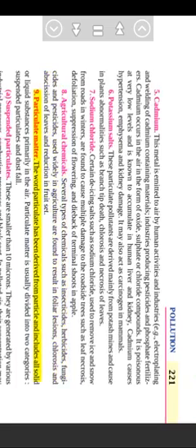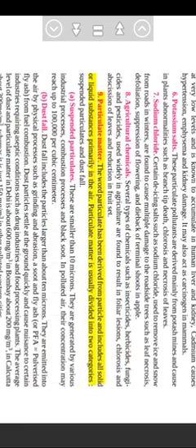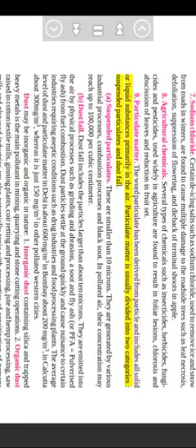9. Particulate matter. The word particulate has been derived from particle and includes all solid or liquid substances primarily in the air. Particulate matter is usually divided into 2 categories, suspended particulates and dust fall. A. Suspended particulates. These are smaller than 10 microns. They are generated by various industrial processes, combustion processes and black soot. In polluted air, their concentration may reach up to 100,000 per cc. B. Dust fall. Dust fall includes the particles larger than about 10 microns. They are emitted into the air by physical processes such as grinding and abrasion, soot and fly ash or PFA equals pulverized fly ash from fuel combustion.